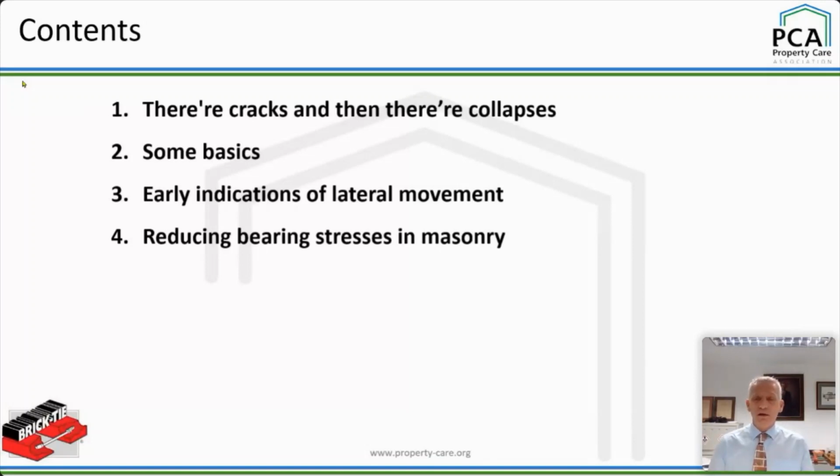And then we're going to look at some more basic things like bearing stresses and reducing them, to underline the importance of the structure and the material that houses are built from. The fact is, they're very soft materials, and we'll go into that. So we don't want to overstress them or use massive patress plates and things that tend to load buildings up. Then we'll look at some defects and remedies. I'm not going to go massively into remedies because there are plenty of people, the Helifixes, Thor Helicals, Peter Cox, wherever. There's loads of people who can organise CPDs for you on all the various methods.